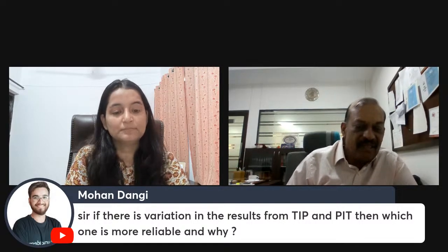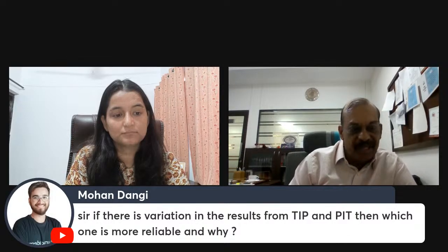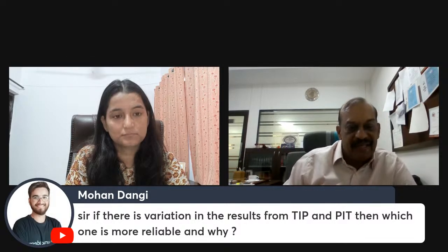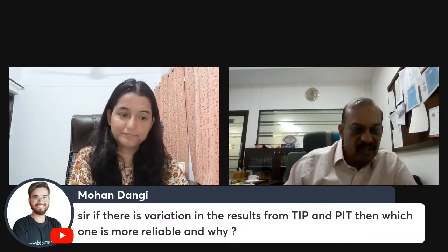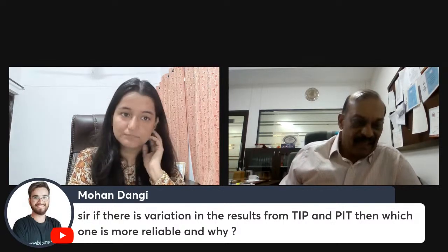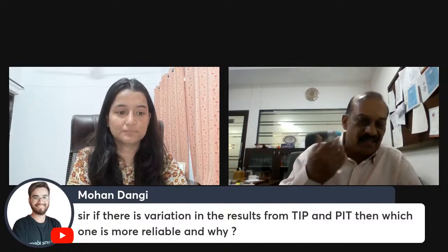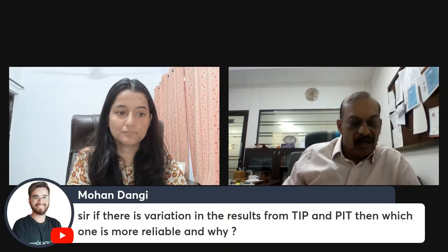Same way, in the case study I showed, the results of the PIT didn't show a proper toe response. You just can't sit on that. You'll have to figure out why the toe response is bad. Maybe you want to do a high strain pile integrity test. Maybe you want to do pile coring.